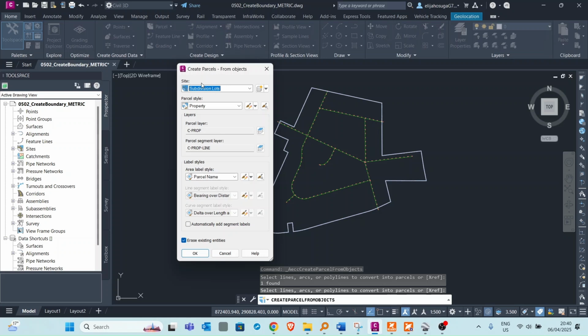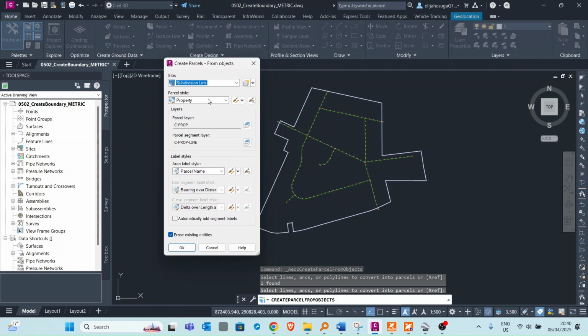So remember, in Civil 3D, parcels usually reside within sites, and a site is a place where different Civil 3D objects are able to interact with one another, as we will see. So these polylines, these alignments, will interact with the parcels of land, because we will put all these alignments into this site as well, and we'll see how they affect the pieces of land.